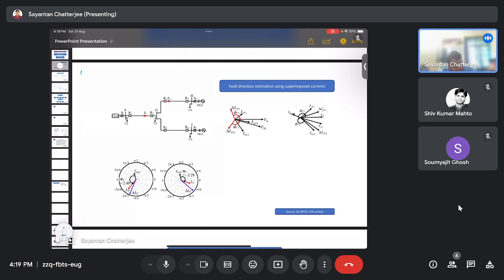That is also known as protection coordination. In protection coordination, based on the positive sequence component, pre-fault case and post-fault case, first relay 1: the time of operation and the setting of this relay 1 should be determined beforehand. And after that relay 2, which is also the backup relay for relay 1, based on the time, should be given some specific time, like relay 1 would be having some time.